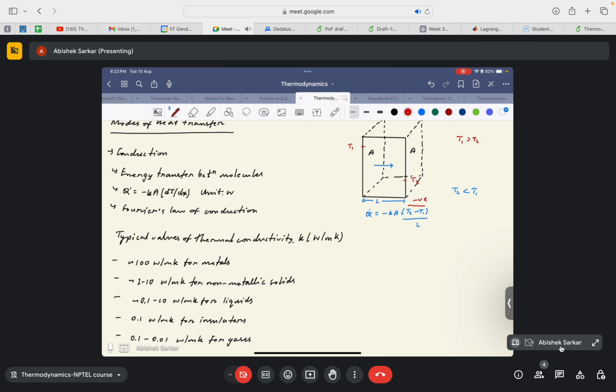So if the net heat transfer turns out to have a positive sign, then the chosen direction of heat transfer is correct, okay. If in some way it comes out to be negative, it will basically mean that the direction of heat transfer is in the opposite direction. So instead of heat transfer occurring from a higher temperature to a lower temperature, if it turns out to be negative, then it is occurring from right to left, okay. So heat is coming out of the wall towards the outward direction, okay. So that is what it will basically mean, okay.